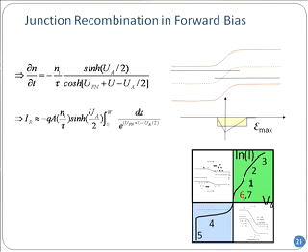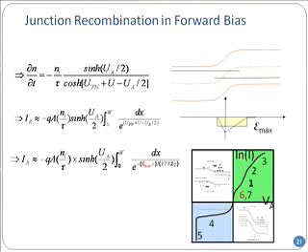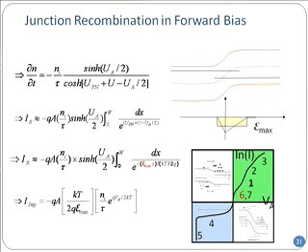Once you have that, you can integrate this, and that requires the integration table, and I will not do that. The only point I will make is that u at x at a given point, generally one can find out from this triangular electric field what the potential is at various points. But in general, that's difficult. So I will replace it with a constant electric field and call that Emax. Then Emax multiplied by x is what u is. This is an approximation, but now I can do the integration. And that's it. That's the integration.